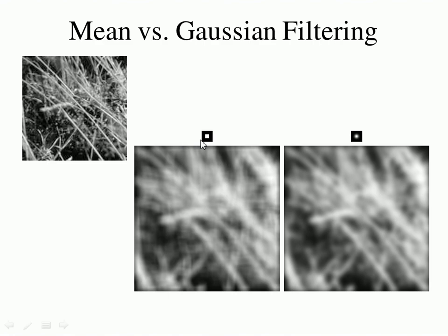So now I take my low-pass filter and run it through, and you can see artifacts coming through. You can see little lines running through the image that have been emphasized by the fact that this has a square edge to it. Whereas here, using this so-called Gaussian filter, those edge artifacts are missing.